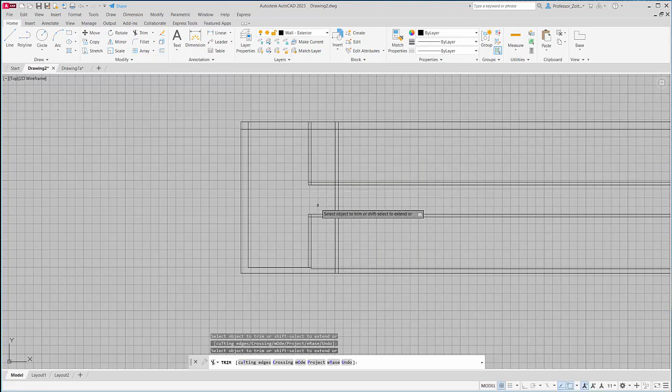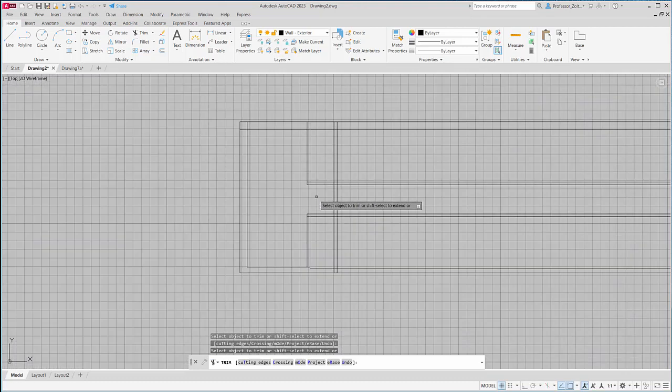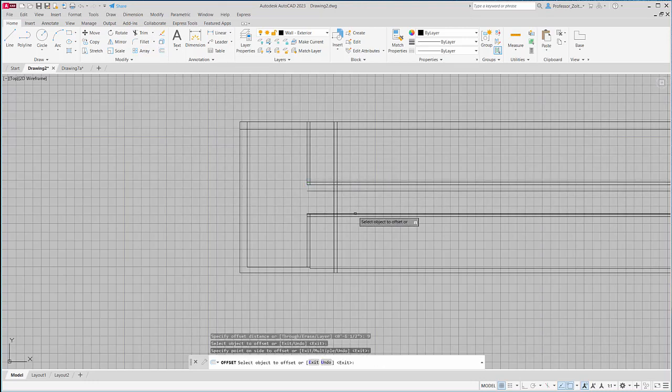And in here I can trim that away as well. Okay, so I have a 4-inch gap here, and I have to look at these segments individually to figure out which is the easiest way. I think right now I'm going to just trim out this door, so I will offset. The door frame looks to be 9 inches on either side of this way, and then I will trim all of this stuff in between. There we go.